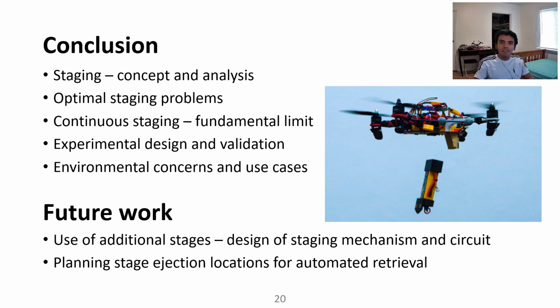The limiting case of continuous staging was covered and we observed a fundamental limit on the flight time regardless of the amount of energy. We then experimentally validated the staging analysis on a custom designed two-stage quadcopter which can eject a stage in flight. We observed a 19% increase in flight time when using the batteries in 2 stages instead of 1. Lastly, we addressed the potential environmental concerns of staging and saw the specialized use cases which can benefit from staging. Some of the possible extensions to this work are also listed.